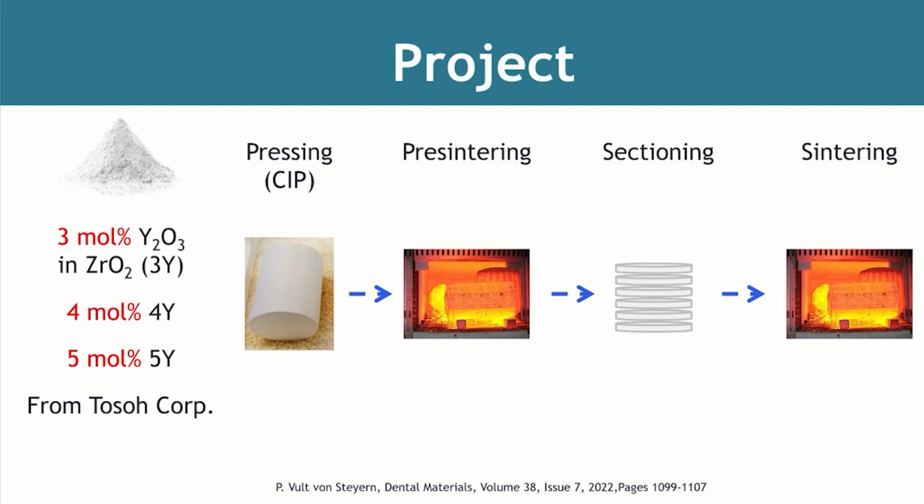In a recently published project, we evaluated 3, 4, and 5 mole % yttria contents within zirconia. We replicated the pressing and pre-sintering procedures commonly done by dental manufacturers. We sectioned the samples for investigation and sintered the samples. The main objective of the project was to evaluate the effect of uncertainty of your sintering furnace.